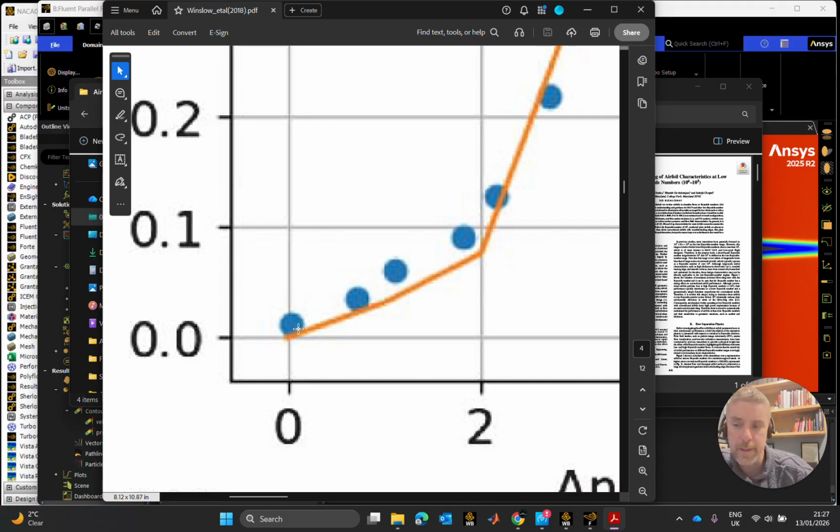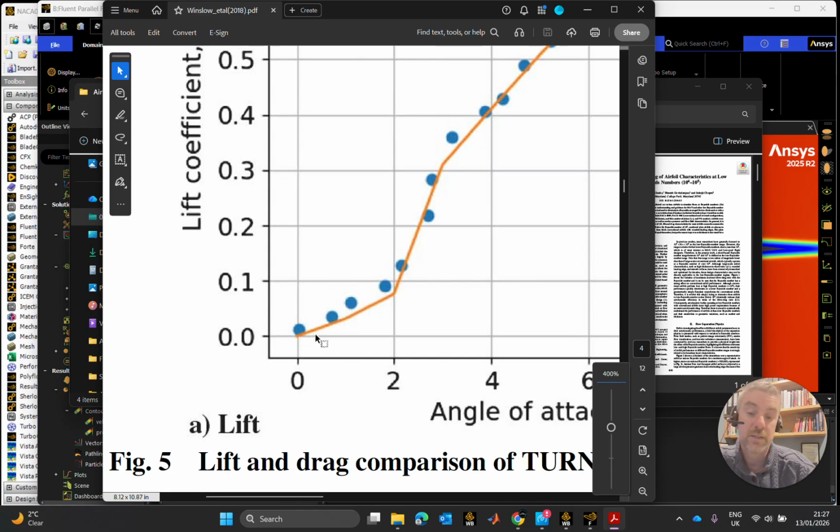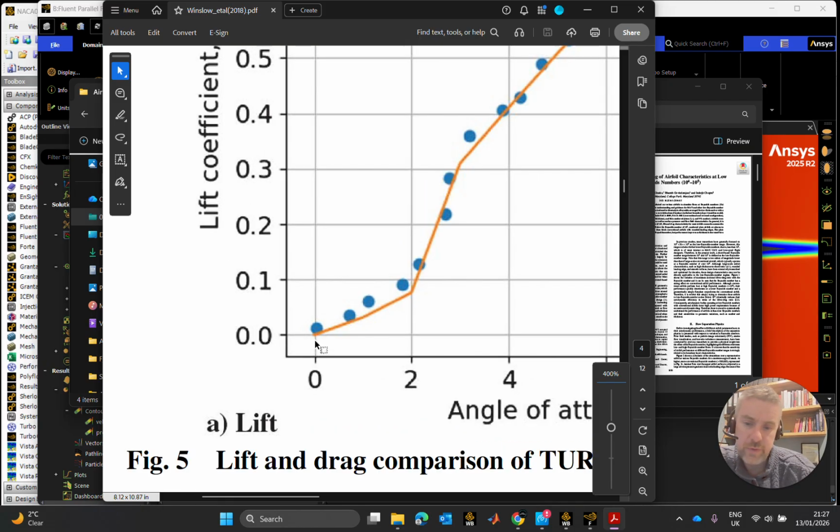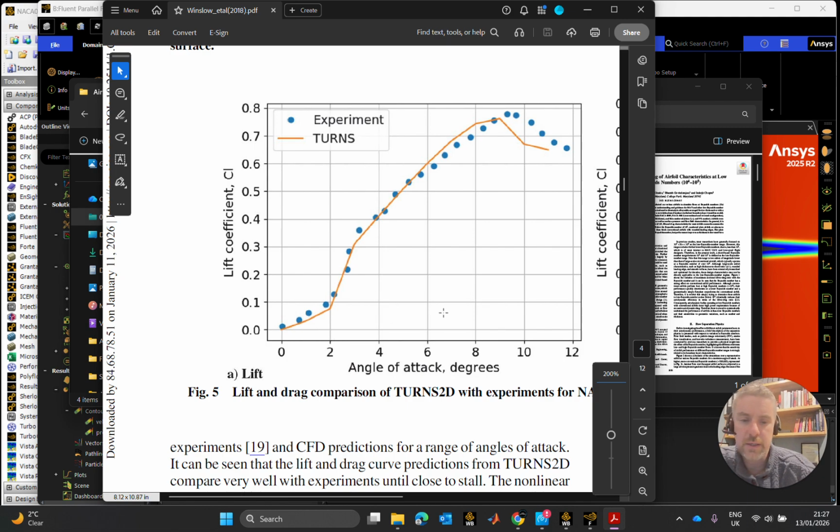Lift on an airfoil with 0 angle of attack, we're really only going to be looking at magnitude, because it could equally go to lift as downforce on that. So that would state there that even if this dot was down this side here, it wouldn't make any sort of difference. The fact would still be the same, in that we have an imbalance, obviously, of pressure over the two sides of the airfoil. It doesn't matter which side it is because it is symmetrical. However, that broadly agrees with what we have. We have a very near zero answer to that.